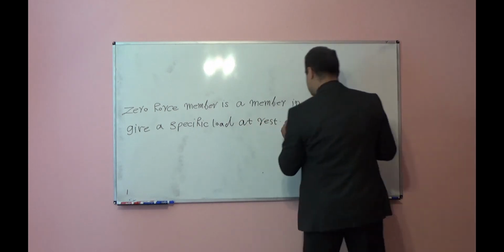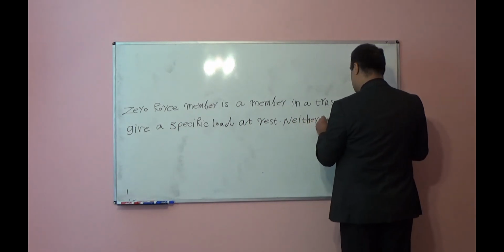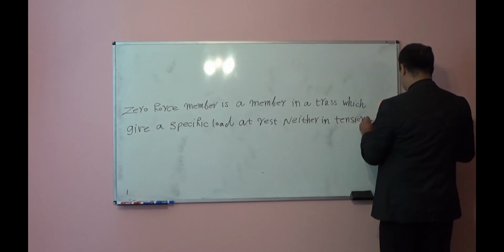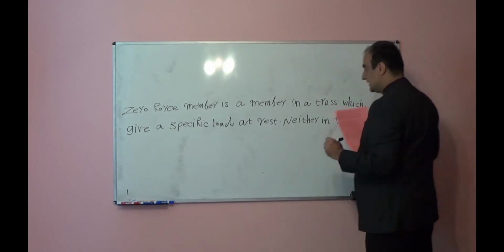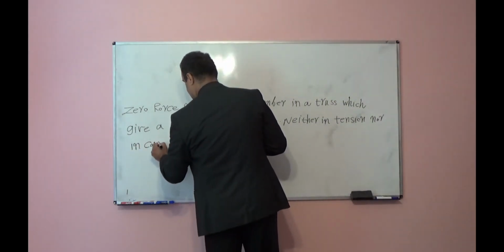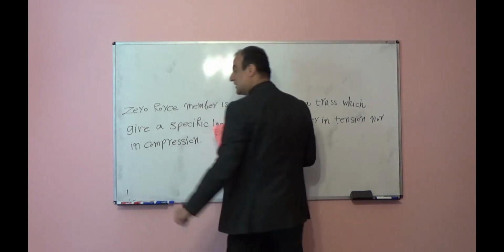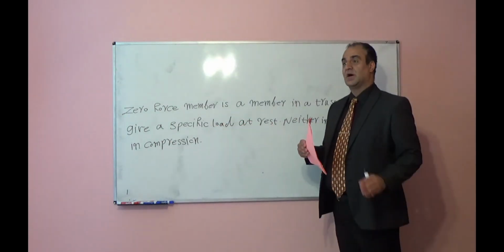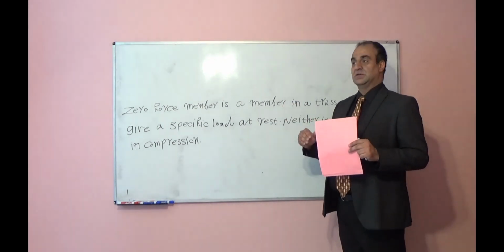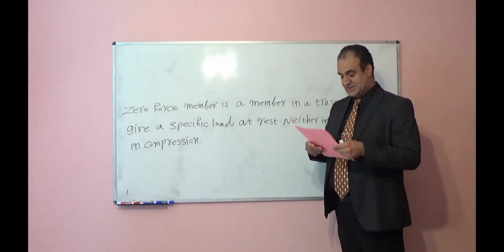It means neither in tension nor in compression. So internal force for that member under those loads we apply at nodes, and we neglect the self weight, is equal to 0.